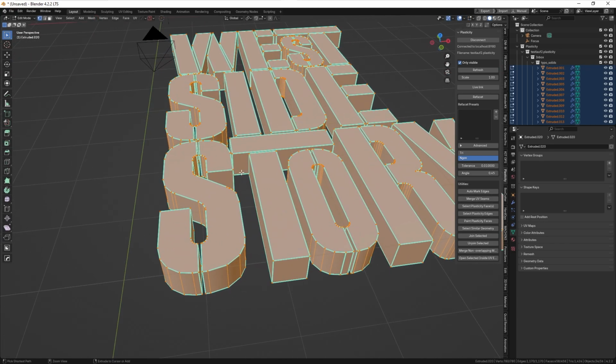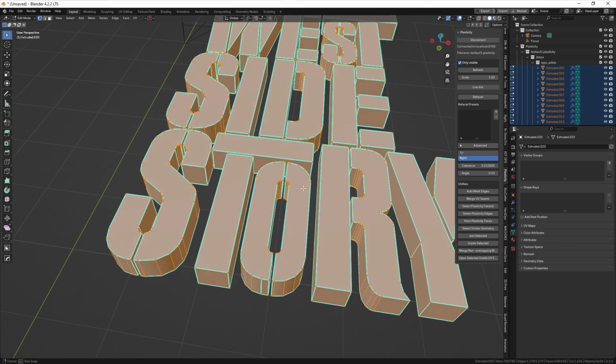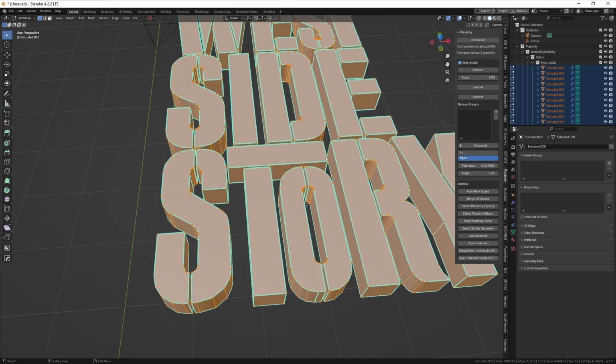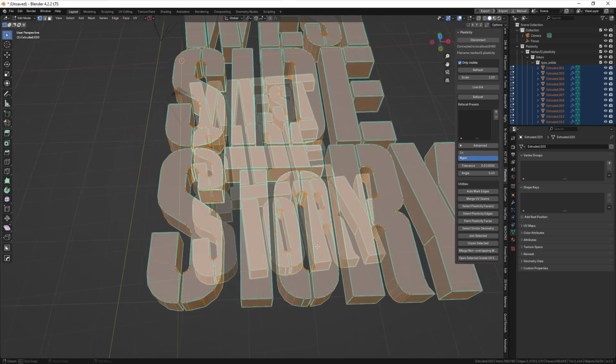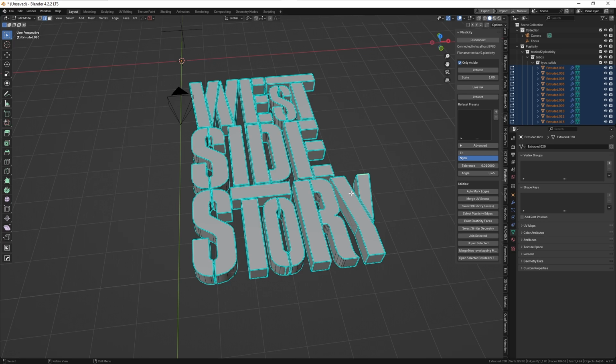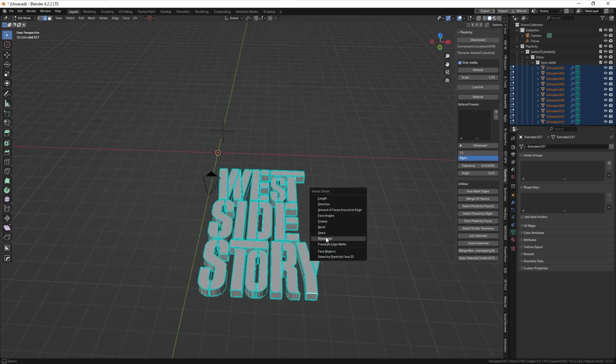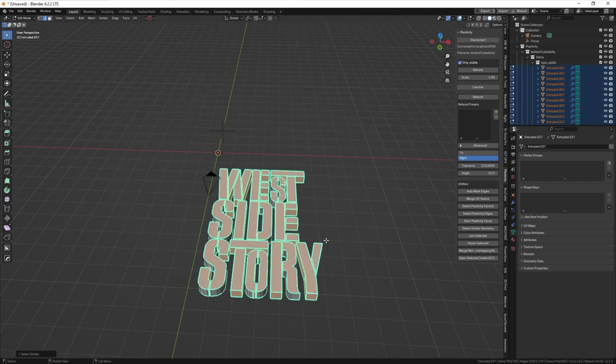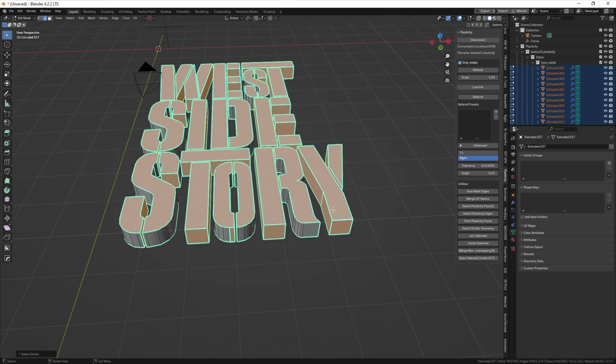Now we got rid of the triangles and our artwork consists now of ngons, which is exactly what we want. One more thing, in edge mode, since we have marked these sharp, these auto marked edges, select one of them, one of the blue ones. Shift G and look for sharpness, so we can select all these sharp edges.